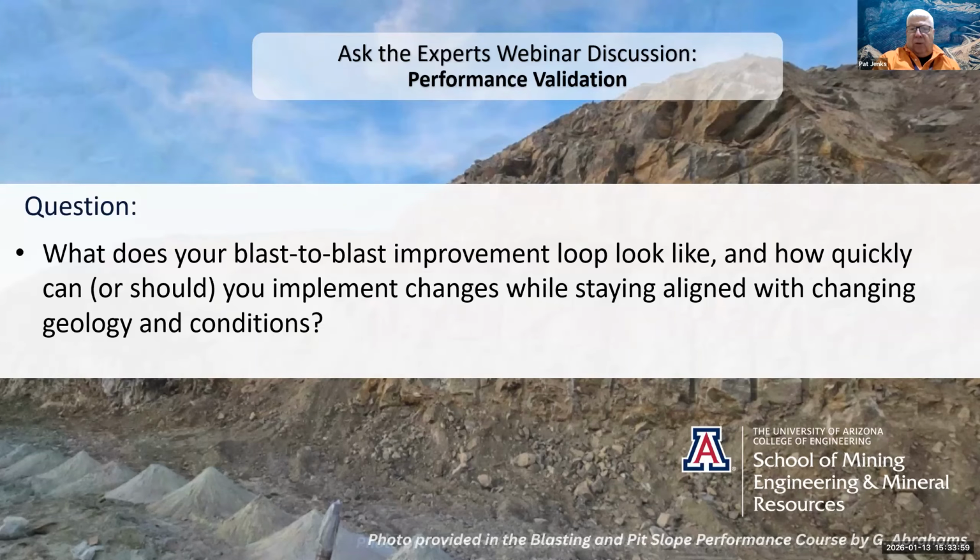Could these be a result of changes in blast timing domains? Are we crossing a fault or lithologic boundary that's causing the vibration to behave differently? Do we need to collect additional signature holes to review with respect to those structures, the lithology or alteration, and develop new blast timing domains? Do we need to limit the shot across potential boundaries and then reassess them?